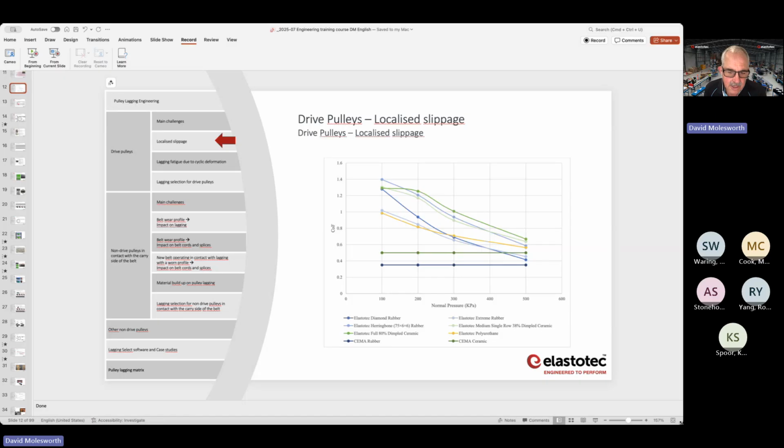When you get that slippage graph and the graph is saying you've got no slippage, it's basically telling you that the friction that you've got is sufficient so that there's no slippage. I'm sure there's a way of getting the actual number, but I'd have to talk to Brad about how you actually do that. Do you want the number so you can use it for other design calculations? Yeah, for conveyor design, for take-up sizing particularly.